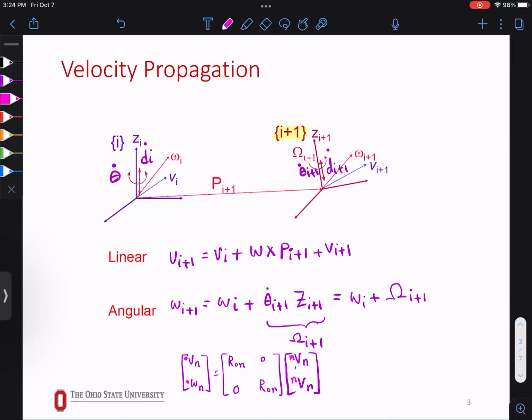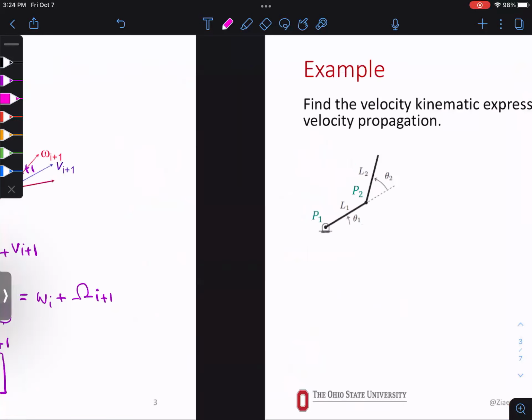So this actually happens if you are selecting the motor. Either you over design and say, okay, let's just pay $500 for every joint, you're going to be safe. Or I'm really tight on money, I need to pick the right motor. Then you need to know the torque that each needs to sustain, plus some percentage of being safe there.